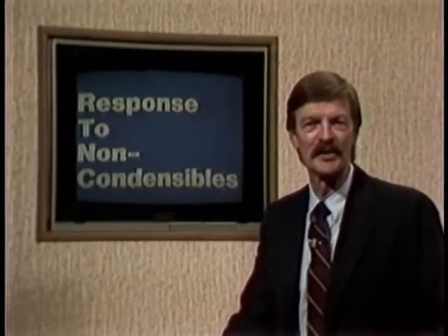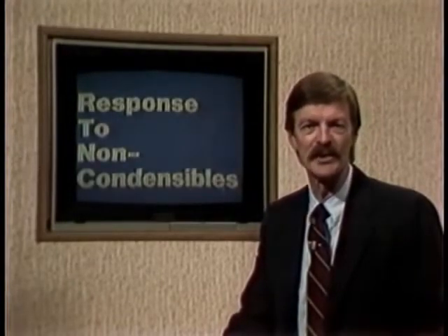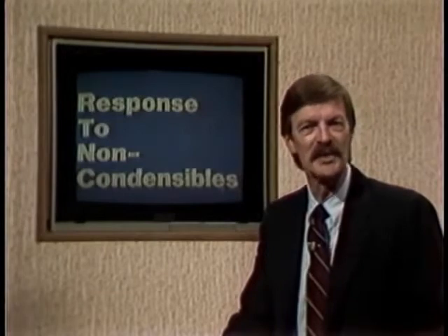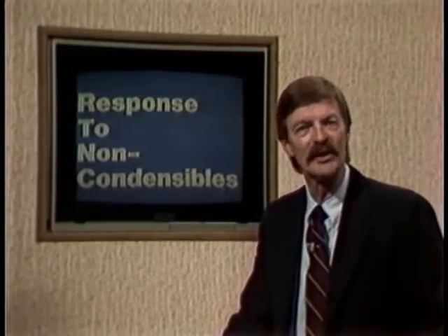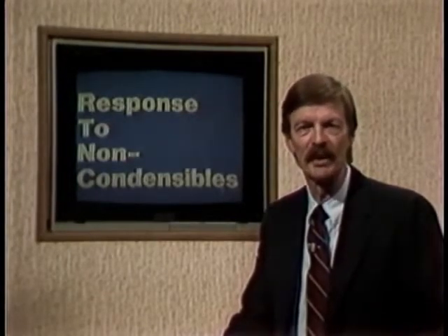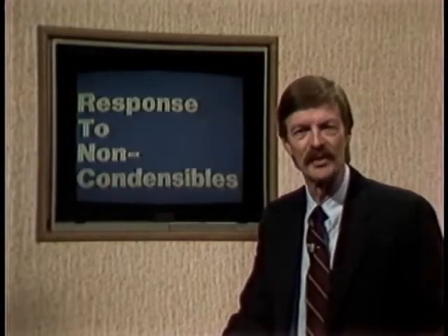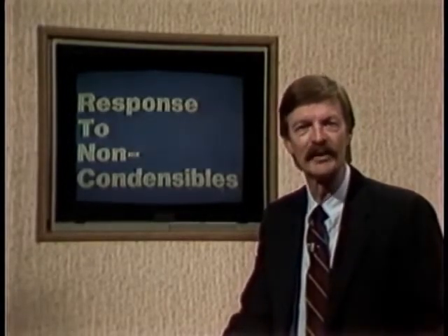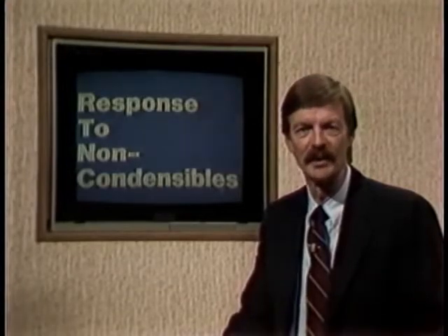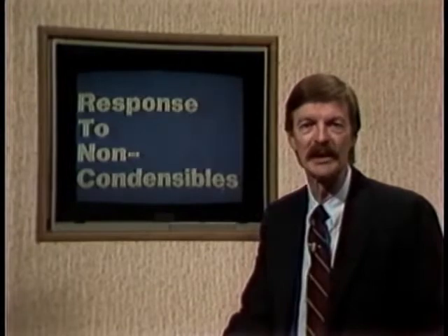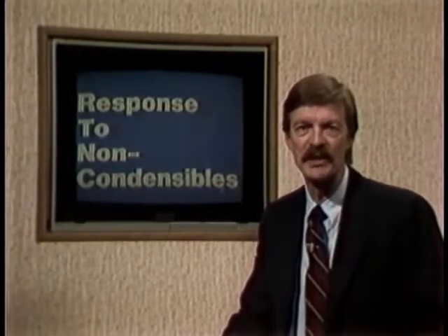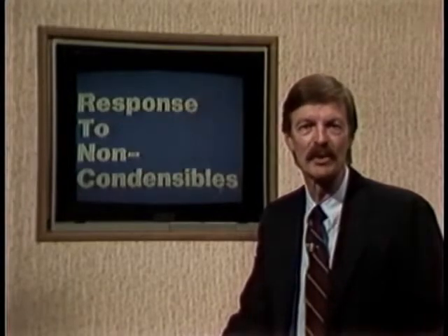Carbon dioxide is the primary non-condensable found in steam systems. Condensate and carbon dioxide coexist when temperatures in the system are at saturation. When the temperature drops below saturation, however, the two combine to form carbonic acid. This acid is extremely corrosive and will eventually eat through piping and equipment. Oxygen is another gas trapped in steam systems which speeds up corrosion.